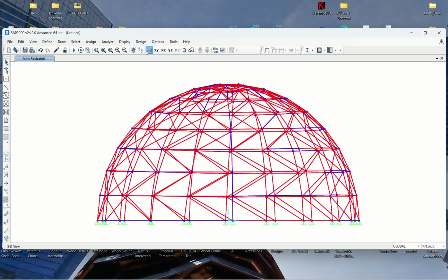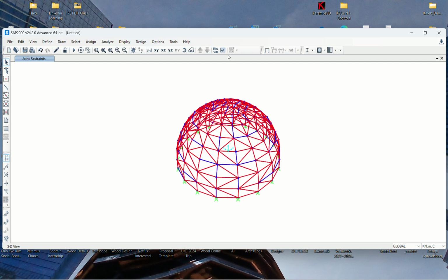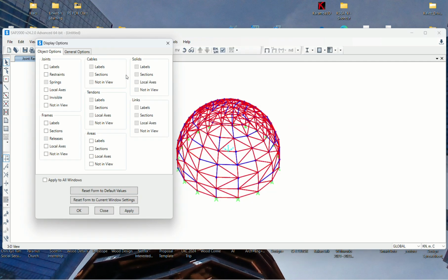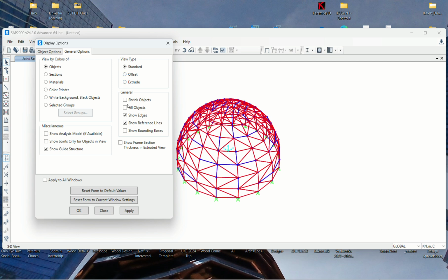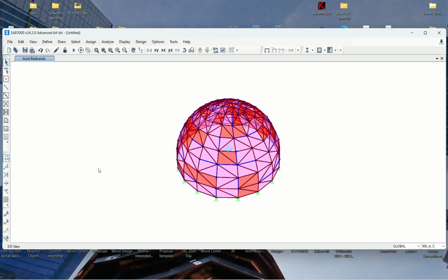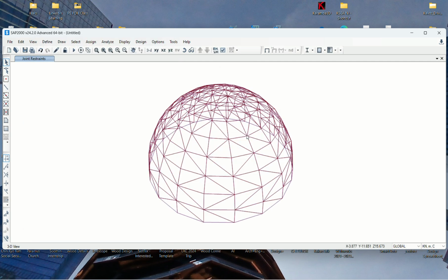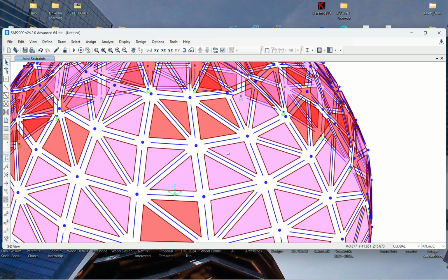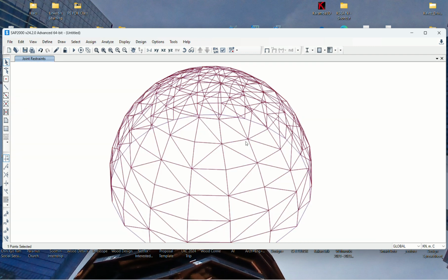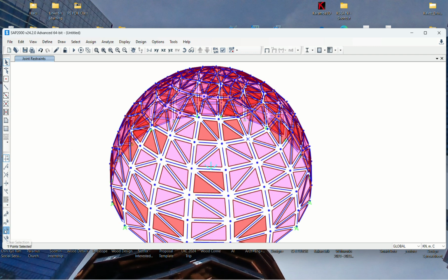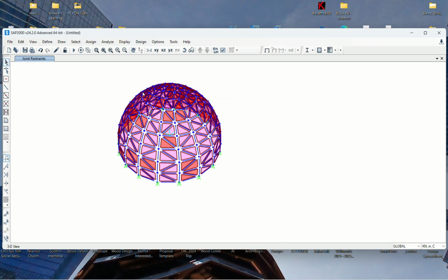This is the pin connection. Also, this shell elements checkbox, I'm going to turn on the fill object so that you'll see this entire. And also, if you want to just shrink, see that all the line works and the triangular mesh is all there. Sometimes, just in case, you could double check that nodes are not, there's one node. Sometimes it has something tolerance related. There will be a couple of nodes and you need to merge it. So this is kind of basic.